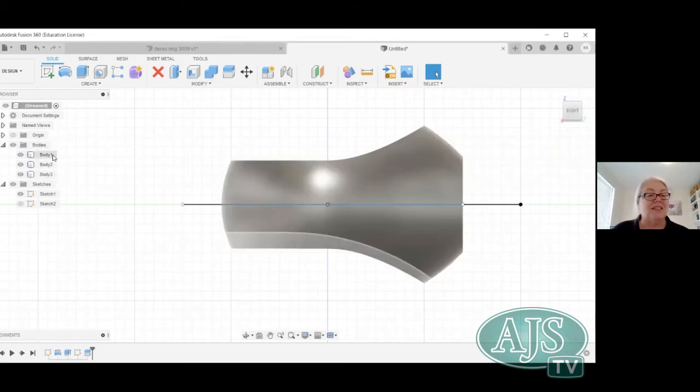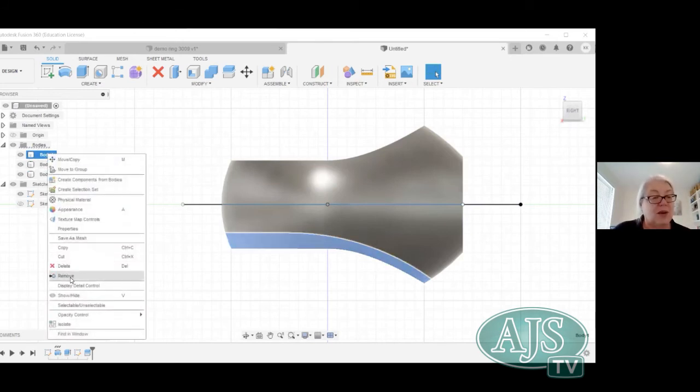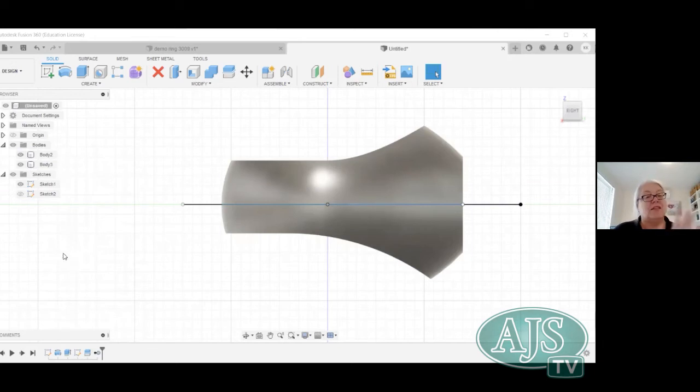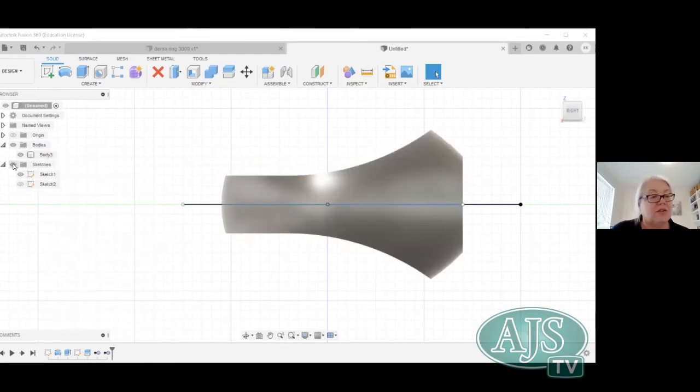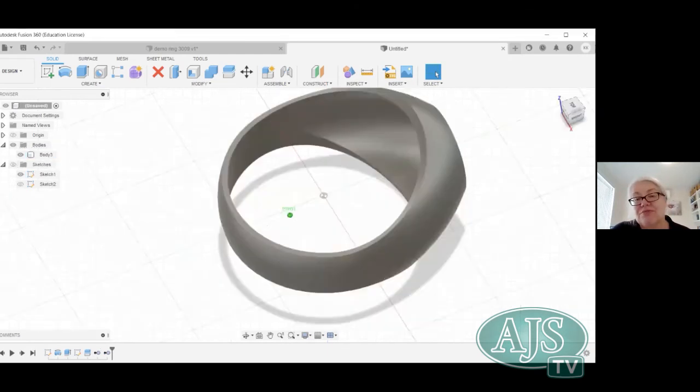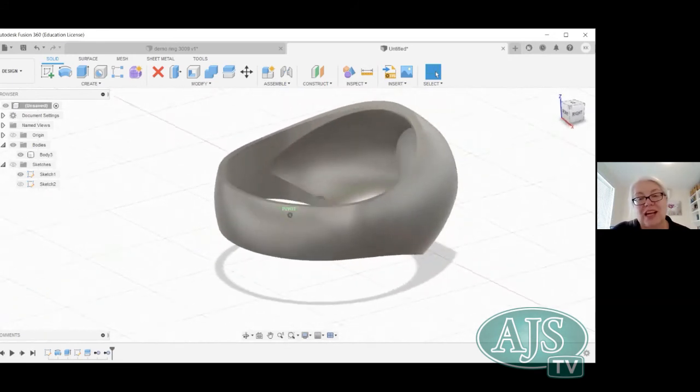Now, rather than hit delete, you can do that, but it can set up some problems later on if you're going to do something more complicated on the top. So often the easiest thing to do is we just click on that and we remove it altogether. So we can't recall that unless we do the Control Z and go back, back, back, back. Now, what's the other bit? We want to keep that. Don't remove that. And let's remove that. So we're just going to winnow these guys off, turn off our sketches. And that's pretty good. Yeah, we're pretty happy with that.